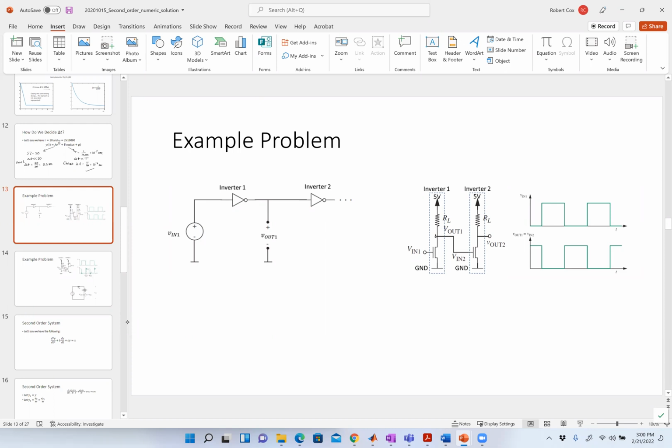When a switch is on, what does the switch look like electrically? A short circuit, right? So I put a voltage on this switch terminal, which more appropriately is called a gate. If I put a voltage on that gate, you can think of a wire between this point and this point. And if there's 0 volts on that gate, what happens between this point and this point? Well, how does the switch work? It's either a short circuit in the wall or an open circuit. This guy is basically going from open to short, open to short, open to short.